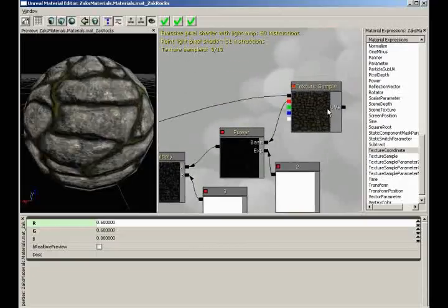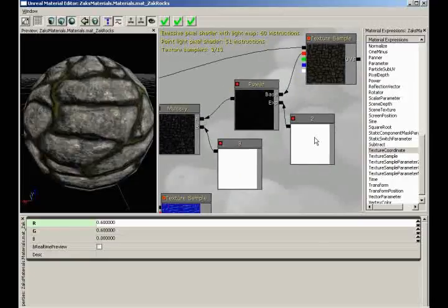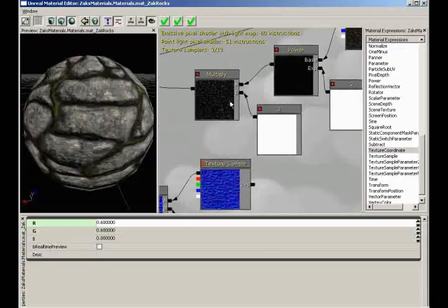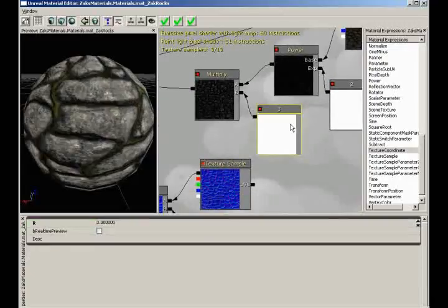You don't have to change it for all of them, just so there's nobody misunderstanding that. It's not a requirement. But for example, we have this constant that's plugged into our multiply node, and this controls how much specularity we're allowing ourselves to have. Currently it's set to 3. If I set that to 100 like I did earlier, things get a lot shinier. So we can take the description and set this to specular amount.